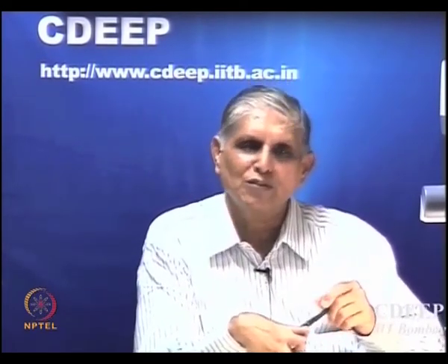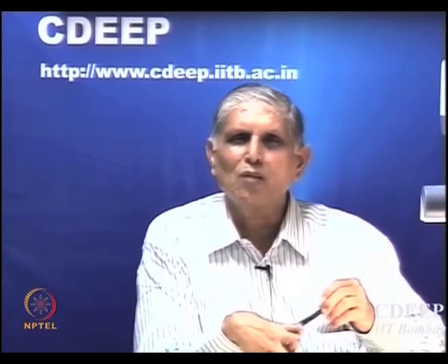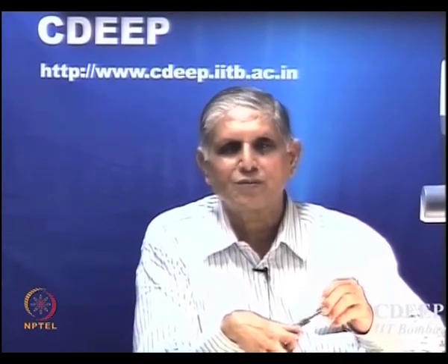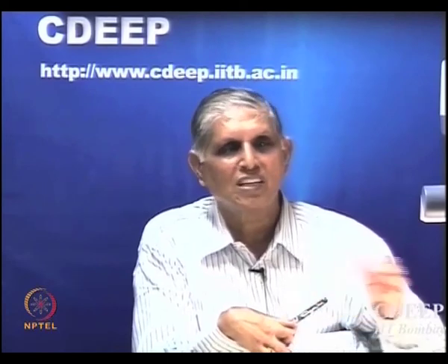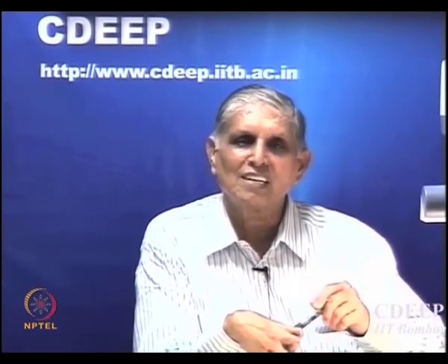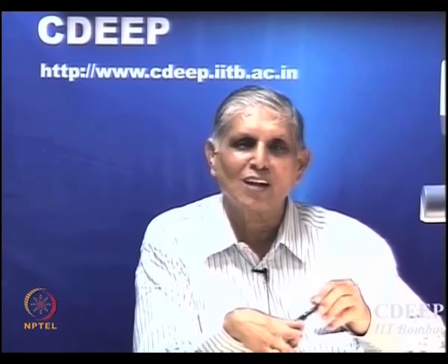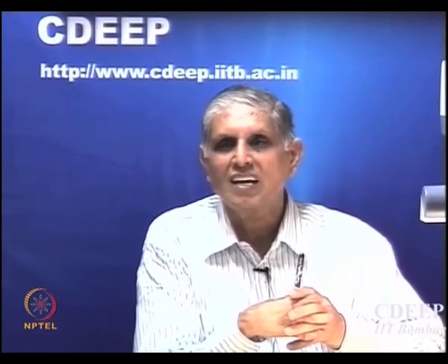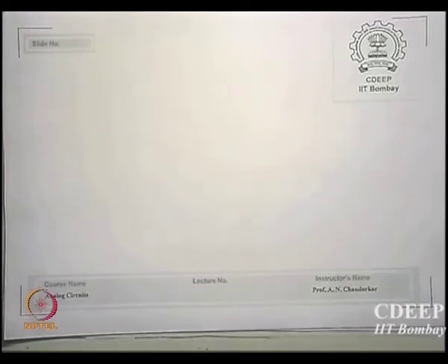Is that okay? So this is the basic phase shift oscillator, which is normally only used in discretes. Why did I say not used so much in integrated circuits? Because I once said realizing an R on silicon is a large area problem, so no one wants to use RC networks as far as possible. I don't say never use it, as far as possible. So these are the issues which you all should know about.